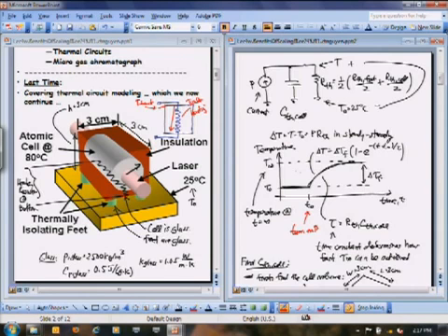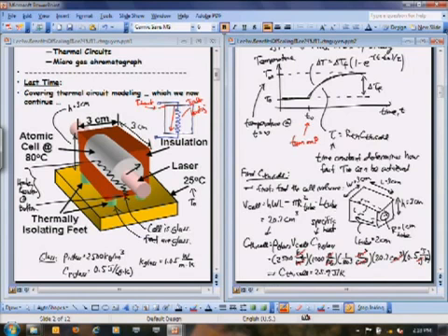And we did that by just following that expression that I gave last time for thermal capacitance. It's just density of the material that you're making the thing out of times the volume of the material times this thing called specific heat. And really in all of this, density and specific heat are constants. Those are numbers that have been supplied to us. So volume is the only thing we have to calculate.